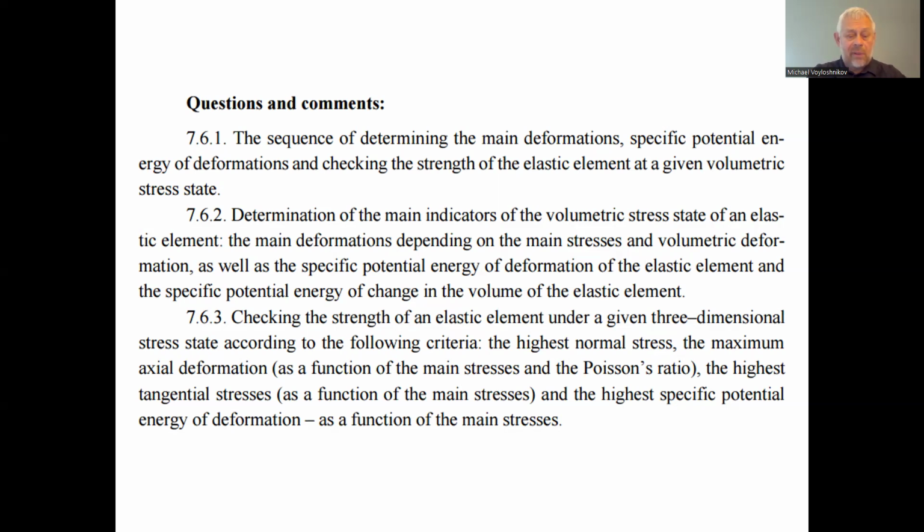Specific potential energy. We have the formula. This specific potential energy we can find in general for the deformation of the segment of the mechanical body under the stress state. But we also have the formulas for determining the specific potential energy spent for the change of the volume of the segment of the mechanical body under the stress state, and the energy spent for the change of the shape of the mechanical body.